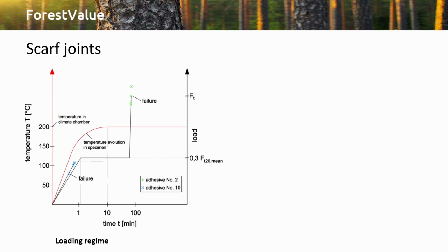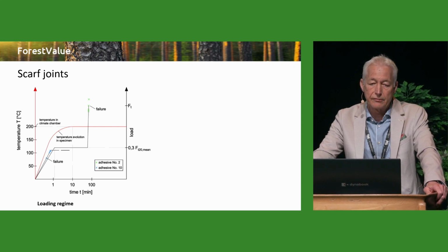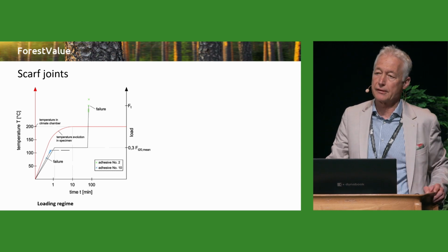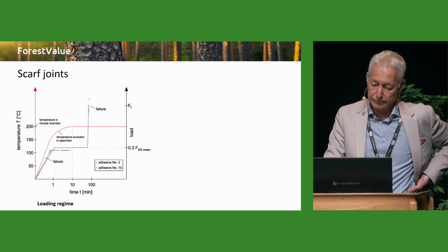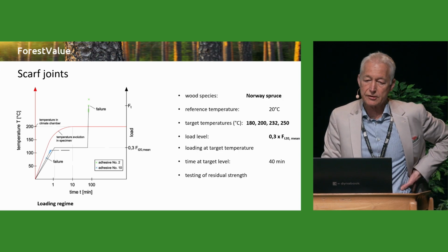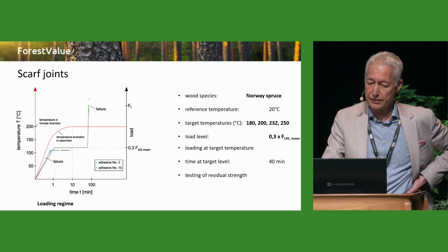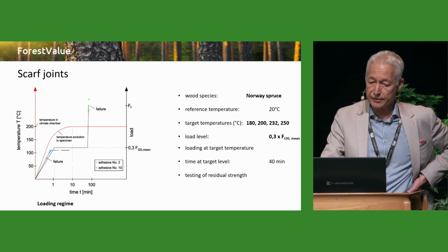Then the load is sustained for 45 minutes, and unless it's broken, the specimen is then ramp loaded to residual strengths. I should say that the load level applied is 30% of the mean ramp load strength. So these tests were performed with the temperatures you see here, up to a maximum of 250 degrees.